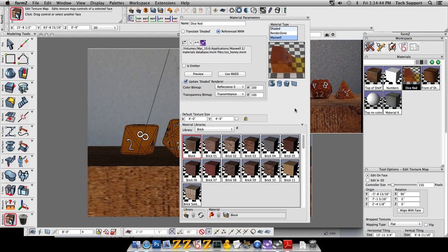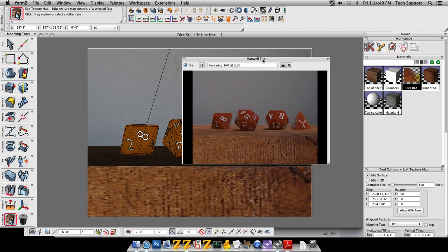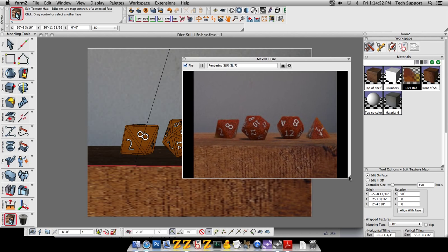If you move the flashlight to the thicker part of your arm, you certainly won't see that red glow because there's no way for the photons to make it all the way through your arm. This subsurface scattering feature is available in Maxwell. It works through the materials, and materials in Maxwell are called MXMs, and I'm going to talk more about those in detail later on. So don't worry about it. Just know that you get some really nice preset ones to play around with at the beginning, and some of these are some nice subsurface scattering materials. Jade behaves this way, where you have a lighter appearance wherever the material is thinner, and a darker appearance wherever it is thicker.